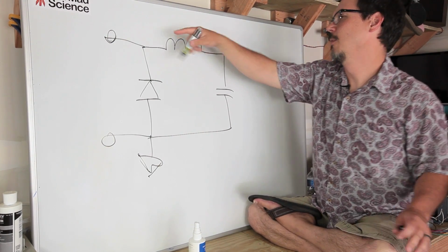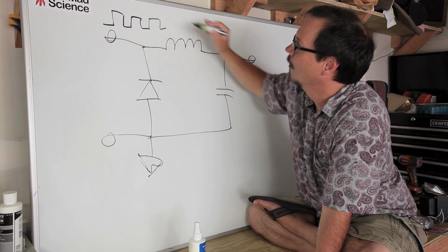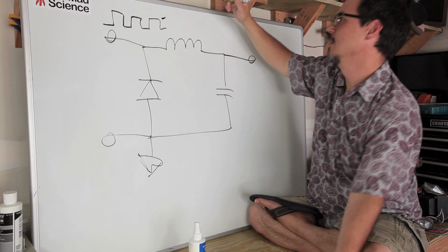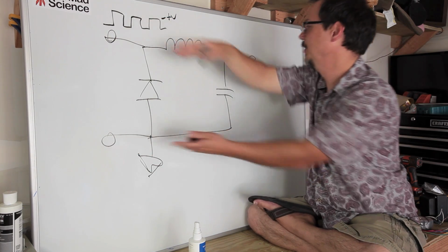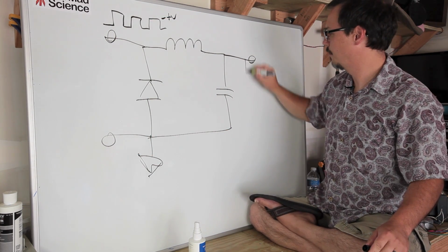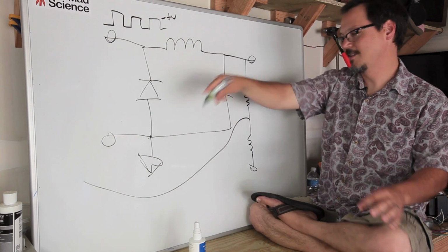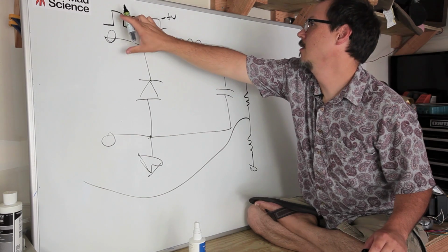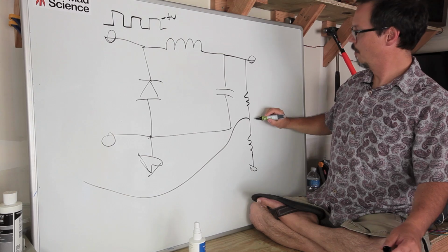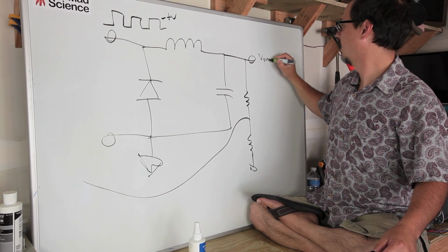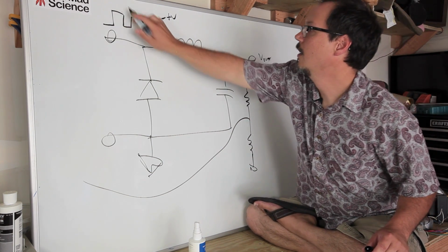Okay, so you've got a high voltage, right? This is the way your buck regulator works. This is your signal in at some voltage, plus V. So what happens is you apply a high voltage here, and there's actually a feedback network here that'll go back to whatever it is that's sensing this, okay? So it turns on a high voltage here, and it charges this up to a point. This is your V out, whatever it happens to be, and it's measuring this, right? And as soon as it gets to a certain point, it shuts off.